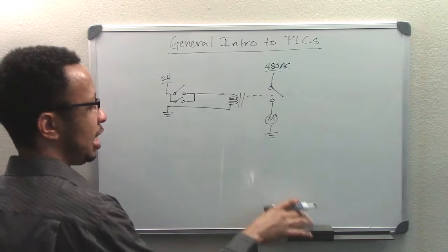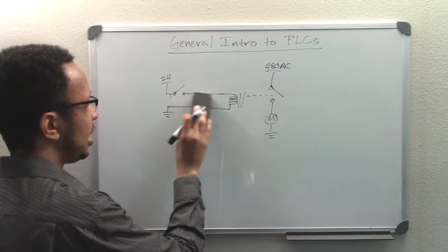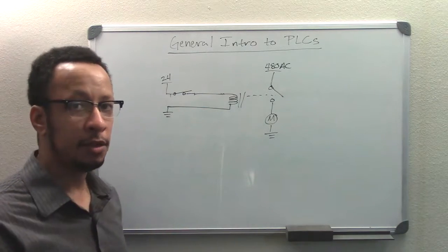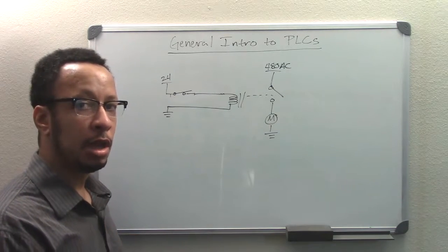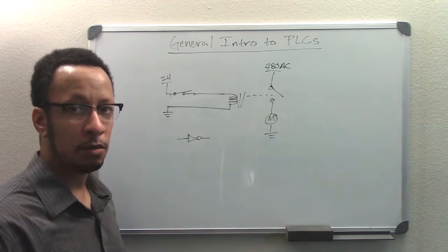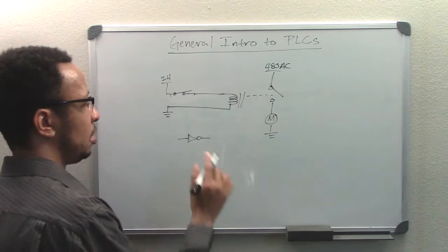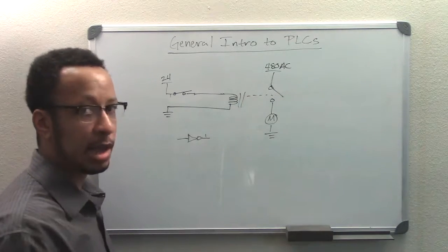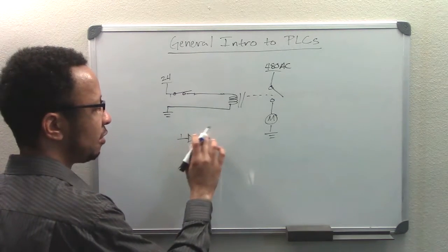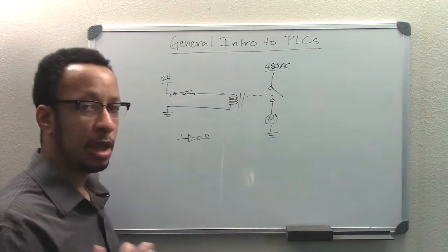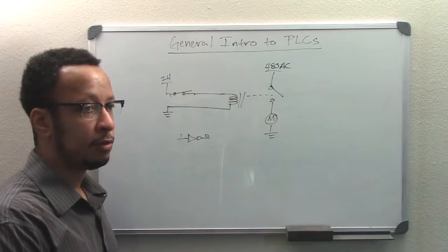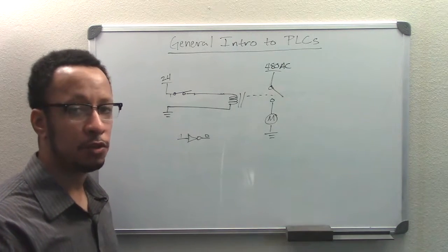By contrast, if we had a switch that was always closed and we had to do something to it, we had to pull on it or push it in order to open it, that would be what a logical NOT function would be. So in other words, if we did nothing, we'd get a 1 there, and then this would be energized and it would turn on that. If we pulled on a switch or pushed on a switch, whatever is needed to open it up, then that means we're putting in something and we'd be getting an open switch, and now because of that, the motor would be off. So that is what relay logic is, and that's the primary basis for programmable logic controller diagrams.